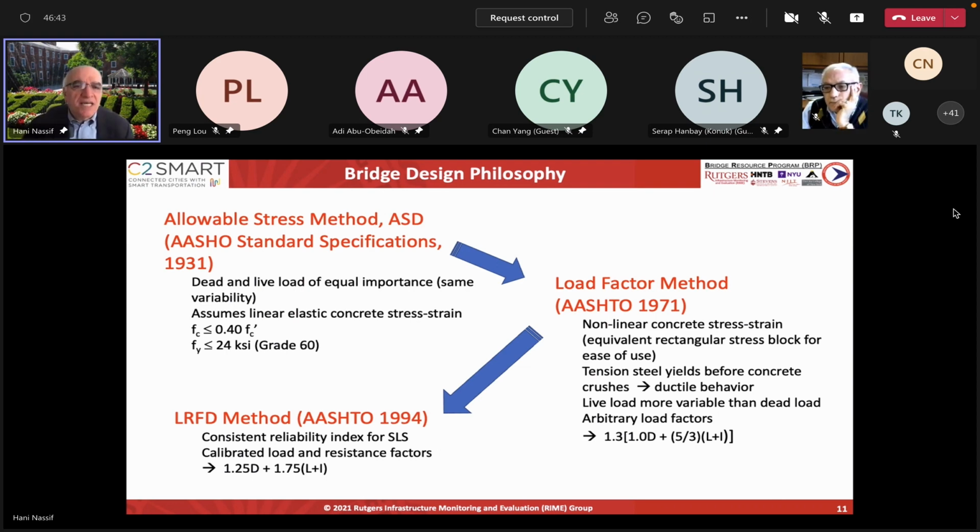So there was a lot of debate about increasing the loads. And then it was agreed upon, because there were so many loads, H20, H15, and then the debate was stopped at HS20 being used. They put -44 to recognize that this was the load adopted in 1944, because there were so many other types of loads suggested.